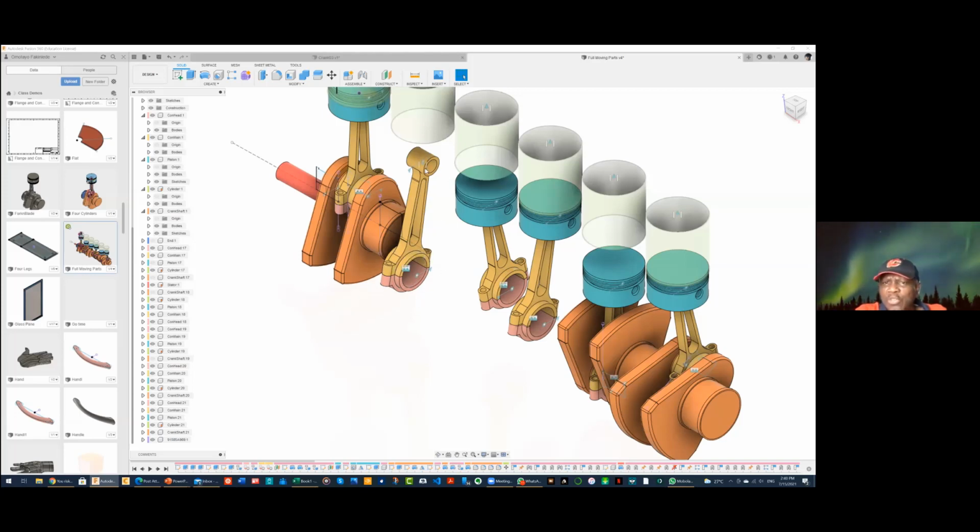As for the top end, we didn't do it that way because we can just put it inside the piston and use a pin to hold it into the piston. But we cannot do that here because of the complicated nature of the crankshaft. Here you can see that a single crankshaft is just a repeating pattern of these two supports with this end. Once you replicate that in a pattern, we have all of that. All that happens in the other ones is that they are just rotated. Apart from replication, we rotated some individual ones. We will show how that is done.